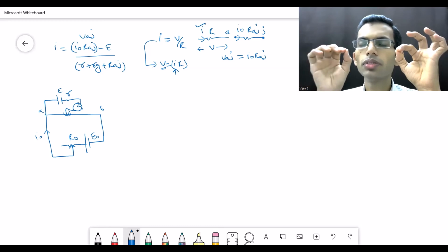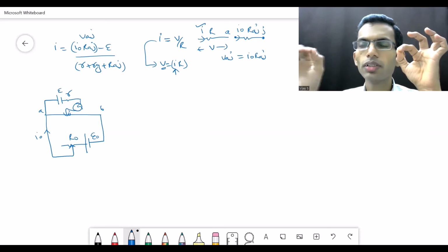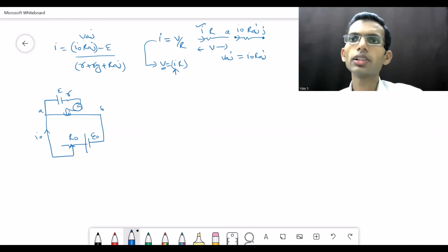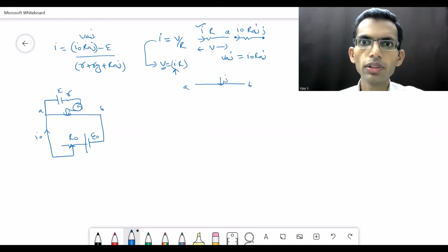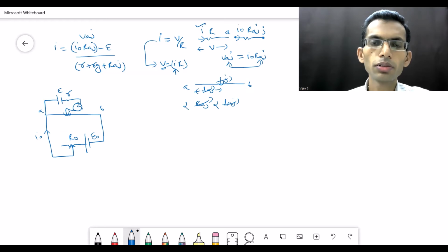The length of the wire between the junction and moving contact position varies. When that varies, the resistance, which is proportional to the length of the wire, also varies. Here you can see the length of the wire between A and J is going to vary, and the potential difference, also proportional to RAJ, is going to vary too.